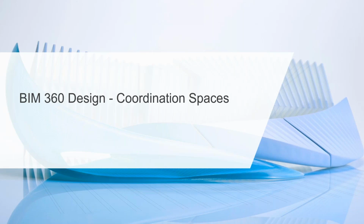project. In your Plant 3D coordination project, the files will be stored on BIM 360, but this is not just used as cloud storage for your central project. You can also use functionality that's offered via the browser. Again, you need to know as a participant on a collaboration project that you shouldn't do core file operations like uploading, downloading, renaming, or locking in the browser with Plant 3D files. It's all managed by Plant 3D.